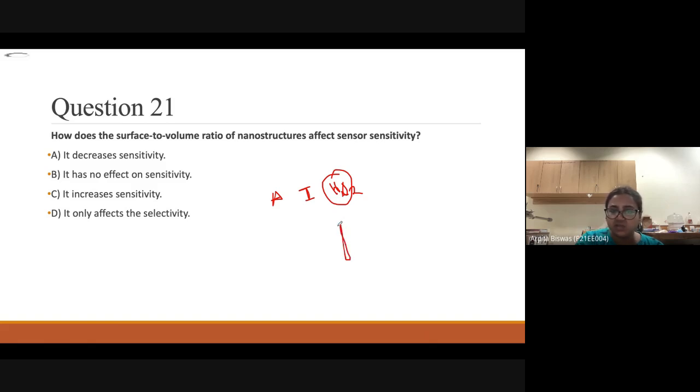This is the structure. This is like 70% or 80% response we are getting for hydrogen peroxide, and for acetone it is giving 5 or 10, and for IPA it is giving 2 or 3. In that case, this device is called selective toward the hydrogen peroxide. So this is about the selectivity. It means it is detecting particularly one selective gas or VOC or molecule rather than the other molecules.